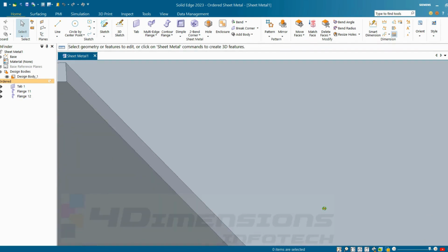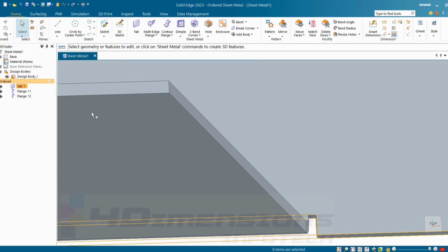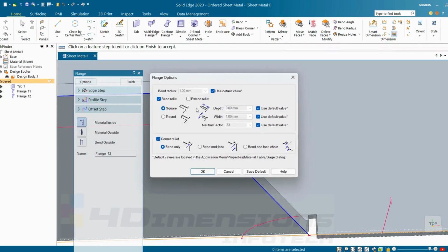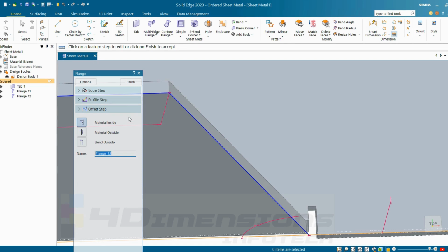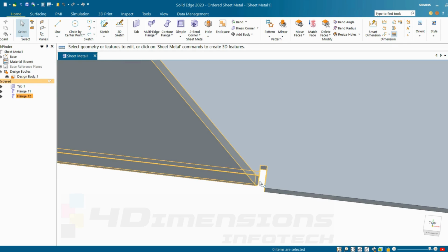And now I want to edit the auto relief gap here. I want to put some depth also here for this relief gap. So I'll say flange, say edit definition, go for these options, just turn off this option and you can edit the values here. I'll say depth as 1 mm only. You can see the change here now. This depth is increased by 1 mm. Say finish. This may be asked in some sheet metal interviews: why has this auto relief been provided? The reason behind it is to relieve the stresses as well as to avoid the shrinkage of the metal.